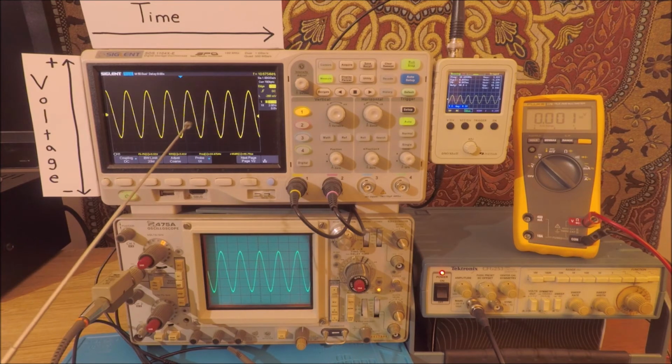The digital oscilloscope up here allows us to program in not only voltmeter and time-based measurements with these soft keys. In fact, right now, it's telling me that the frequency of this sine wave is, in fact, 10.67 kilohertz. But it's also telling me that the peak-to-peak voltage is 10 volts, which is very nice. And it's even giving me an RMS voltage too, which is 3.41 in this particular case.